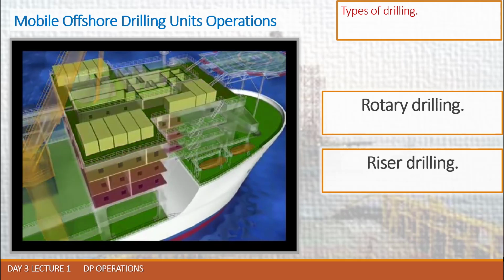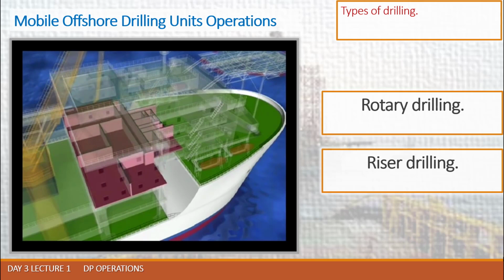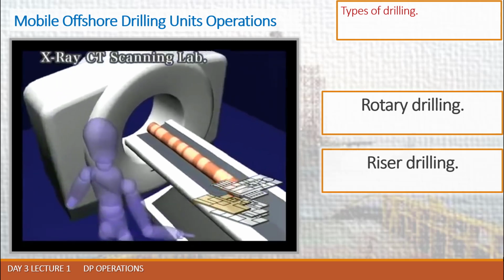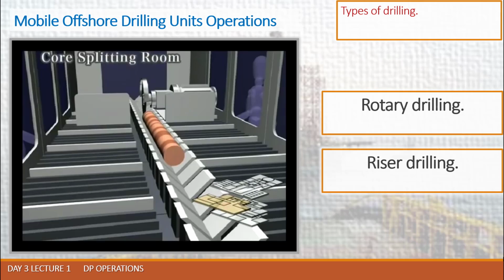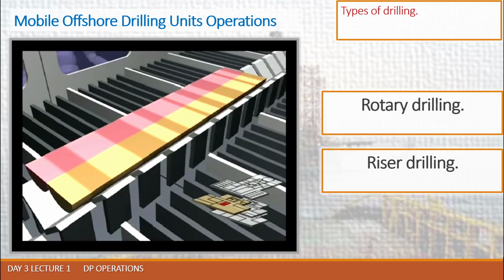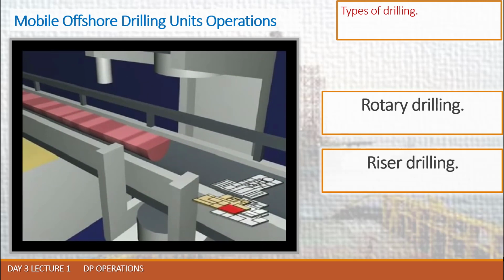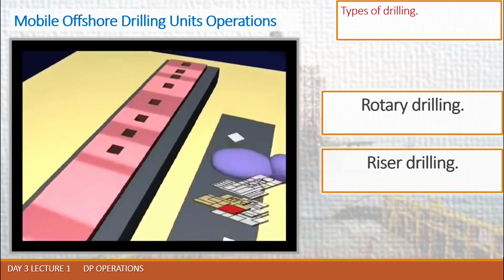The Chikyu contains 4 floors of scientific laboratories. Here is how the analysis of the cores proceeds. First, each core sample is cut into 1.5 meter segments. The core's contents are scanned non-destructively. Then cores are split for study and preservation. Core properties such as density, heat conduction, and sound velocity are studied. Small samples are also extracted from the cores.